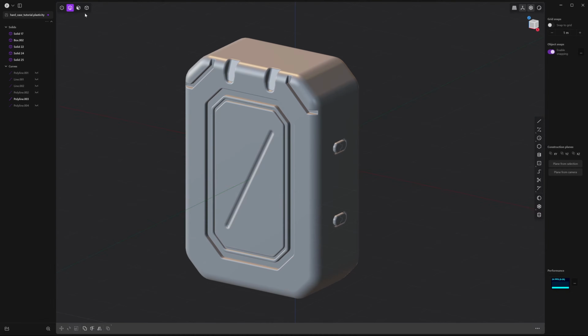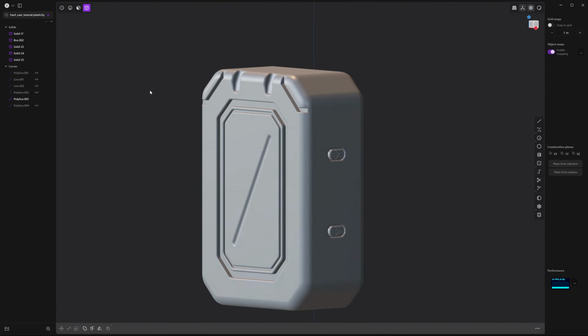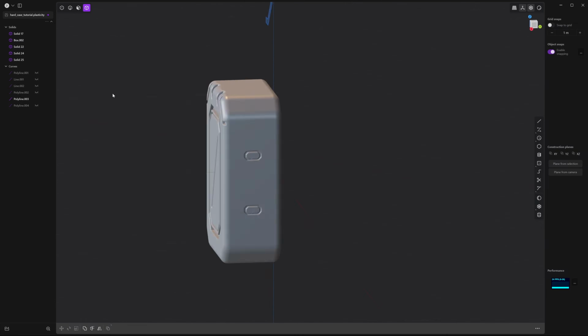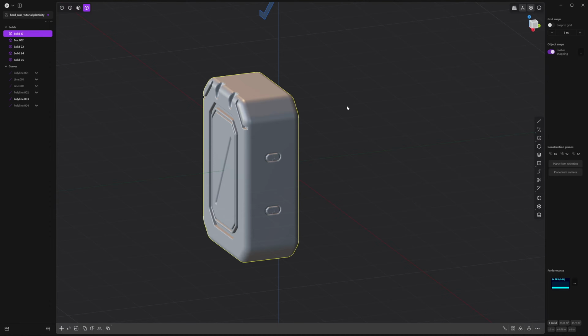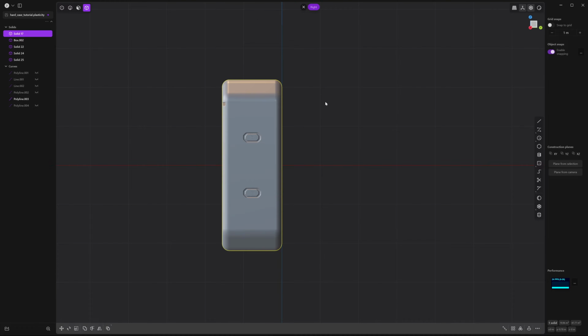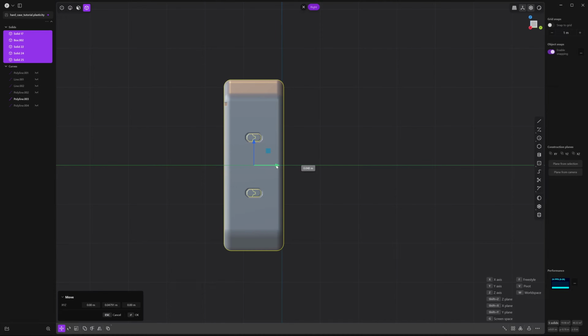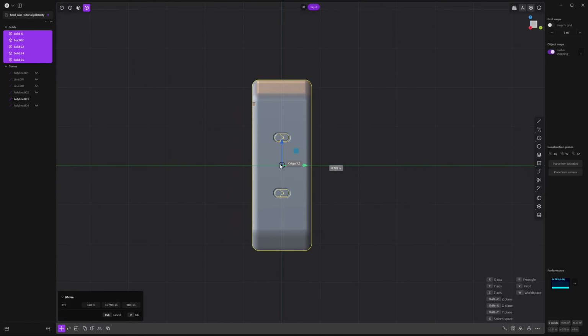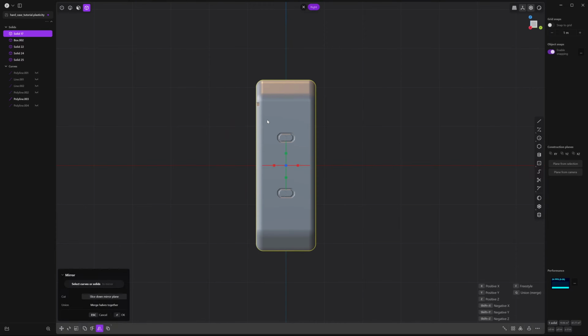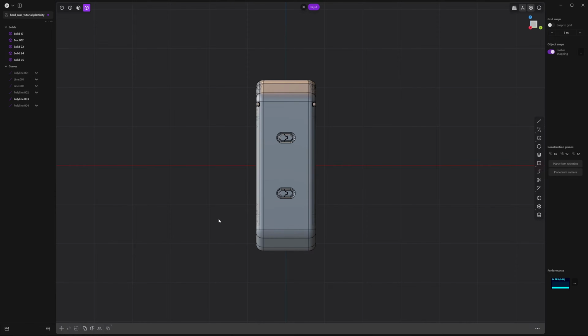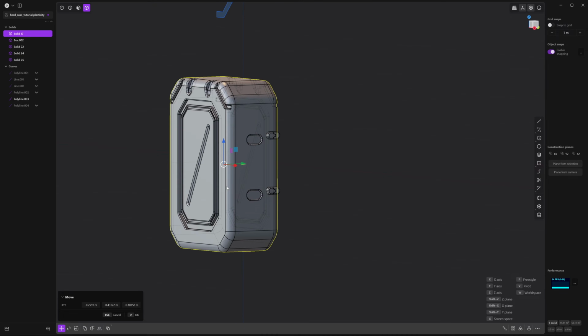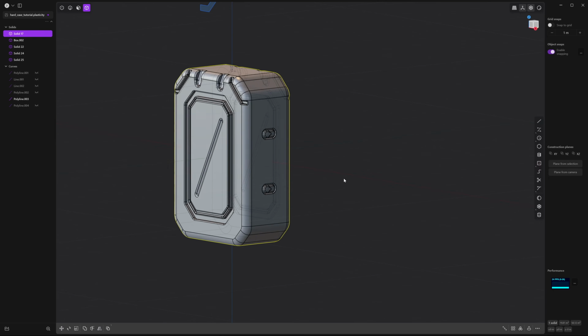Okay, great. So now we have our main body finished, and we want to make sure that details are on the back. So you guessed it, we're going to select the main body and mirror it. But you see it's not in the center line, so we might have some issues. Let's just select everything and move it down the y-axis. Holding Control, you can snap to the center of the origin. Right click to accept. Alt-X to mirror. Don't forget to press merge halves together and right click to accept. And now we have one piece with the details in the front and the back.